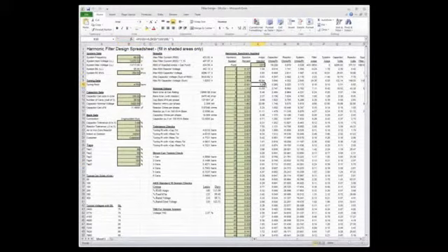This is done all with reactance. There's no resistance put in here. And so you specify an MVA short circuit, system-based frequency, tuning point, your capacitor, and then you put in some spectral content here, and it'll generate the answers for you.